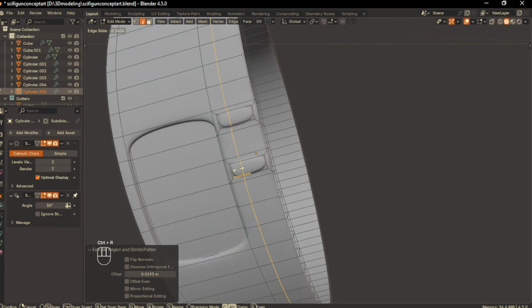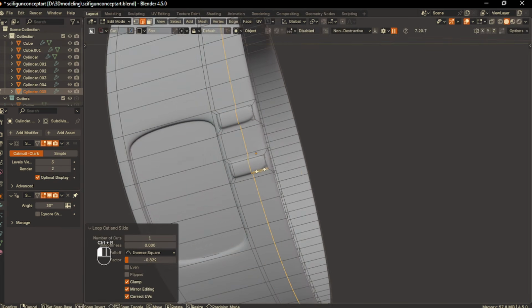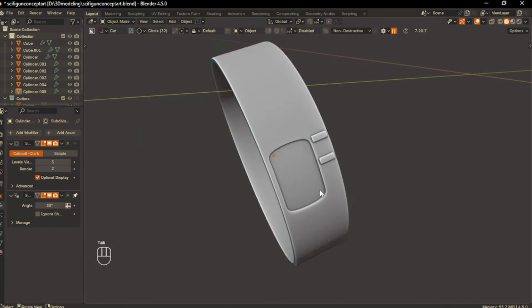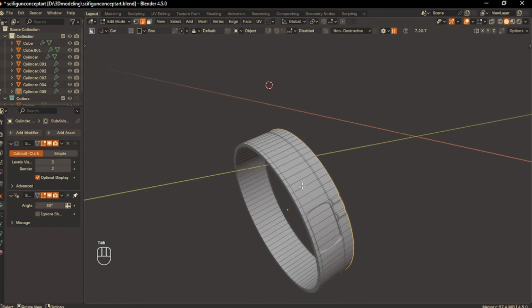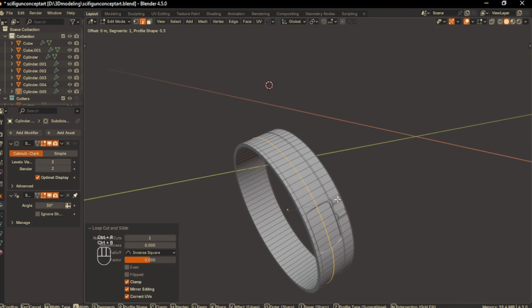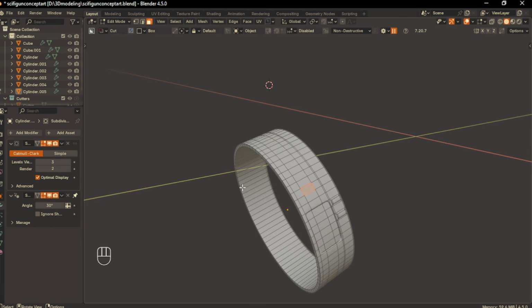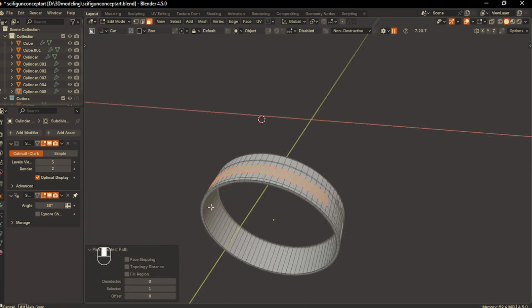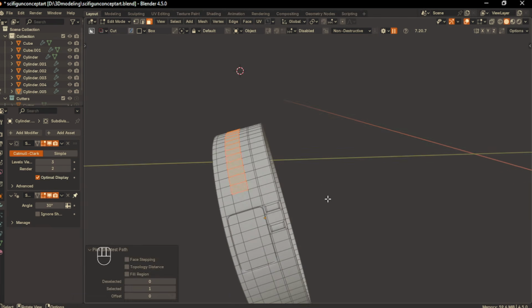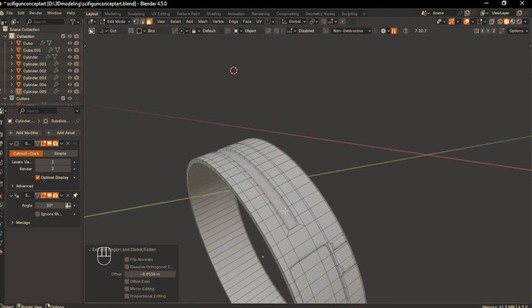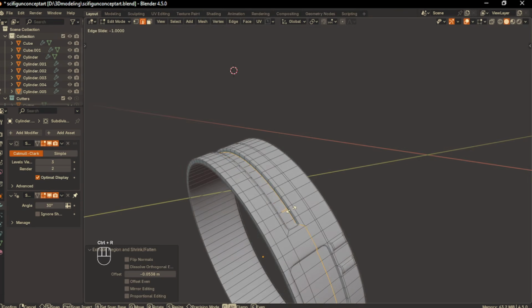and add a loop cut to the far left and another to the far right. Then I switch to edge mode and add a loop cut across, bevel it and then go back to face select. I'll select along this edge, inset the faces and extrude them inward to keep things sharp. I'll add supporting loop cuts at the corner to not lose the shape.